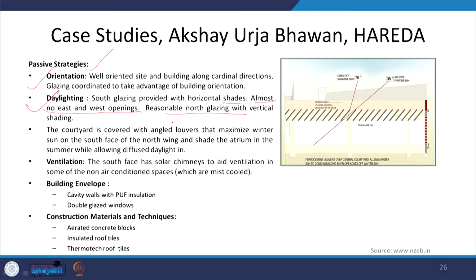Doing this, almost all the areas indoors had a sufficient amount of daylight available. And the building has a courtyard which is covered with angled louvers, which can maximize the winter sun on the south face, while reducing the diffused daylight during summers.